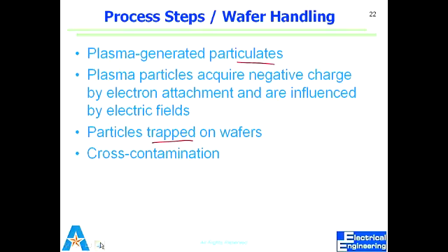Especially remember that oxygen is always a very strong cleaner. Wherever there is oxygen involved in a process, it's a vigorous process. So to clean a chamber, we do a process called oxygen de-scum. Scum is the formation of different materials. De-scum is removing that material. Oxygen de-scum is a cleaning process. We do that very often.